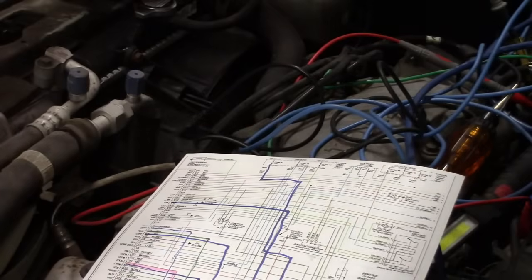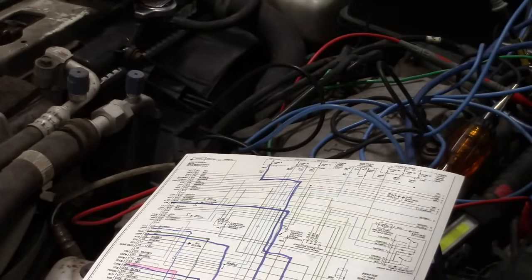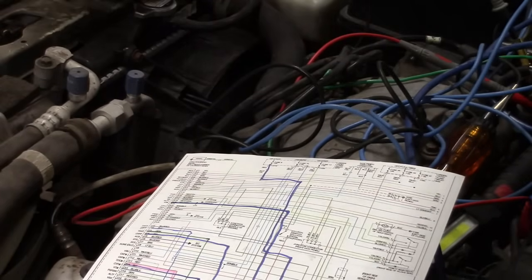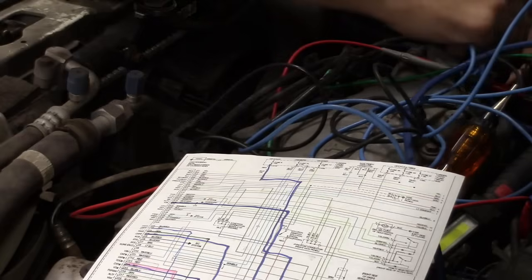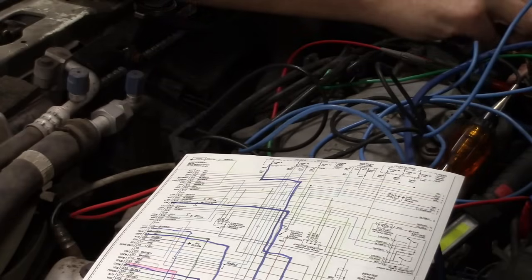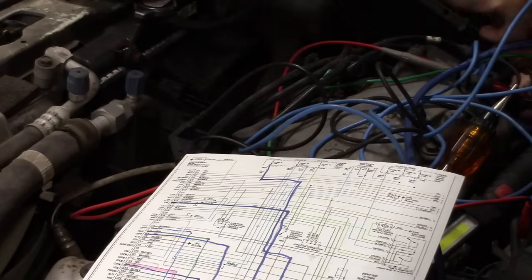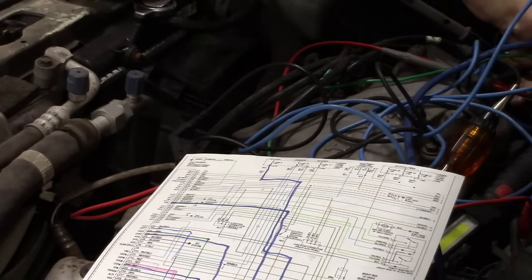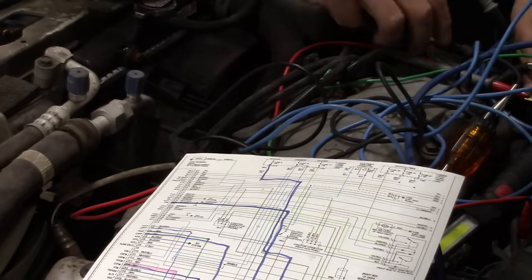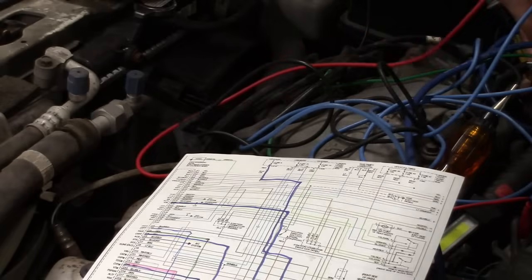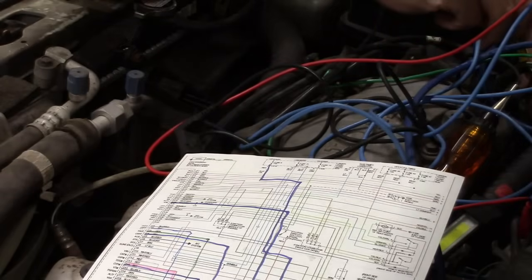All right, and then the other side of the crankshaft position sensor, we're going to have a blue coming in with light blue coming out. That one I know is accurate. I remember, so there's a light blue coming out. I am satisfied with that being the correct one. Back probe him. We'll get our leads on there for our Pico.